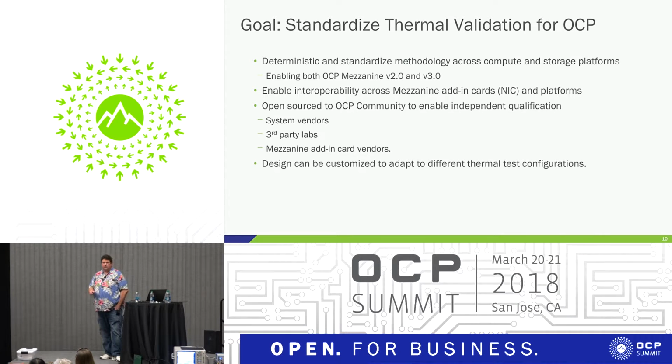So, quickly, standardization for thermal testing for card vendors. From a systems perspective, I'm going to test my chassis and know at what point my chassis fan PWM matches the thermal test fixture, and I'm going to set it that way based on the information that the card gives me initially. Then once the card is operational, systems management is going to tell me what the actual temperatures and margins are, and the system can then modify the fan speeds to keep the system cool. And I think that's pretty standard across the mainstream server vendors today.